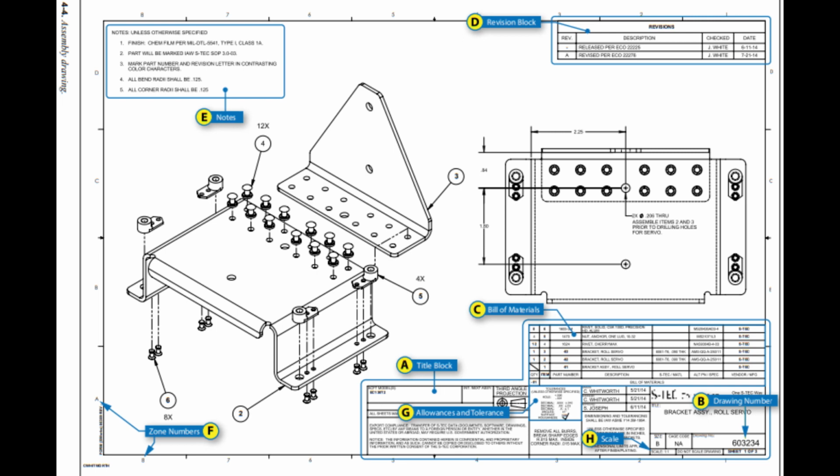Although title blocks do not follow a standard form as far as layout is concerned, all of them present essentially the following information. 1. A drawing number to identify the print for filing purposes and to prevent confusing it with any other print. 2. The name of the part or assembly. 3. The drawing scale. 4. The date. 5. The name of the firm. 6. The name of the draftsman, the checker, and the person approving the drawing.